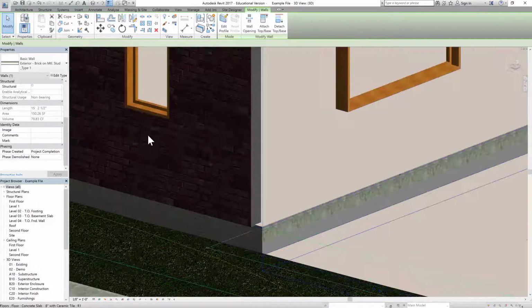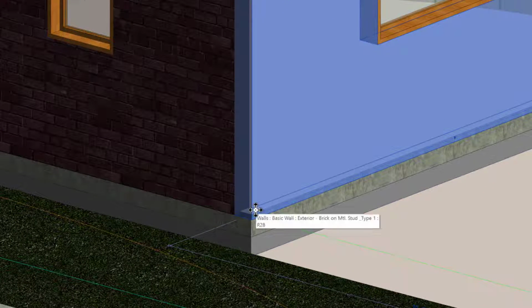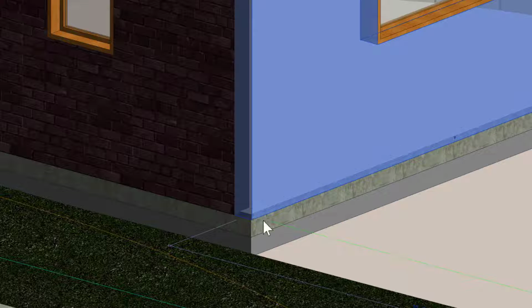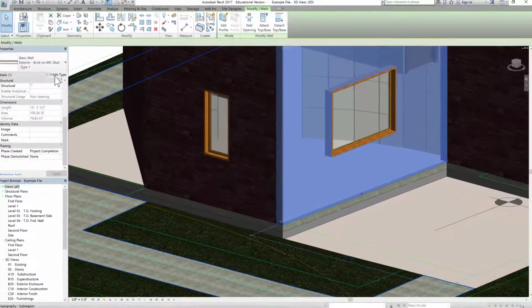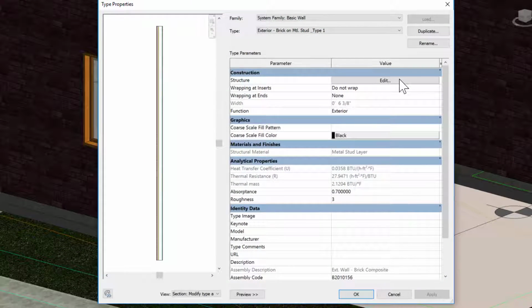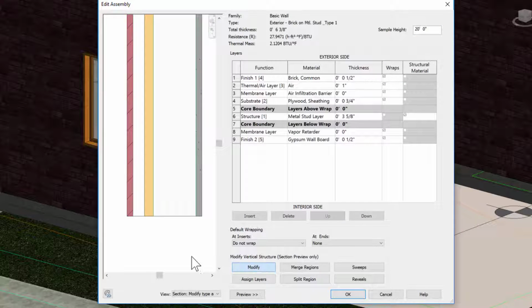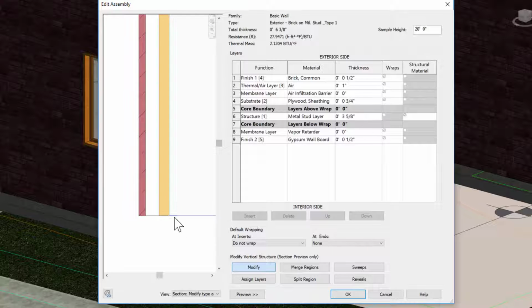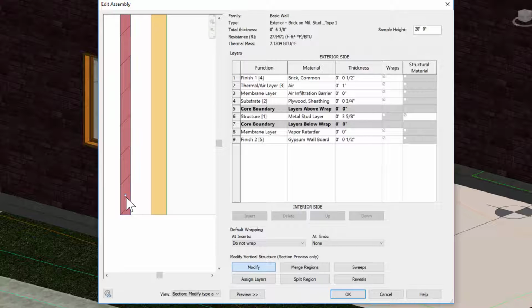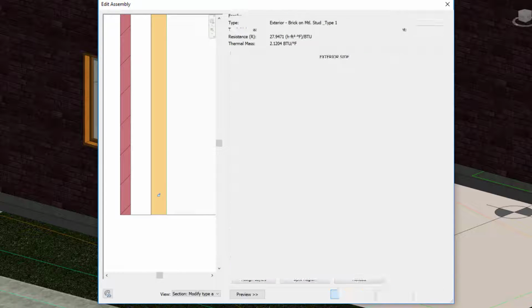What we want is to unlock the layers of this wall, those layers that we want to come down and cover this floor. So let's do that. Let's go back to the wall type, click Edit, click here, zoom in, click on Modify. As you hover your mouse, the edge will highlight. When the edge highlights, click on it and there's a lock, unlock it. Click on this air gap, unlock it, click on this plywood and unlock it. So we unlock these three layers, click OK again.